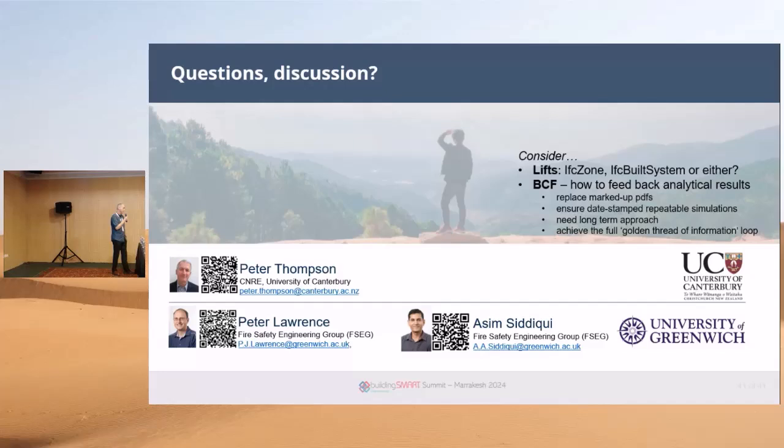So, we had a volume, but we did not really represent the actual geometry of this cable, of the width. In our IFC representation, we just had a tube, but we had single segments with an IFC spatial zone, so that the meaning of the entity is correct.